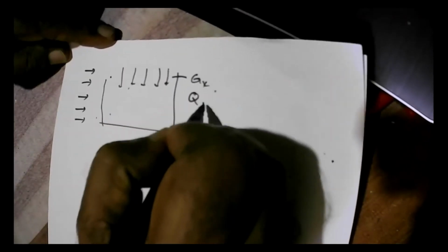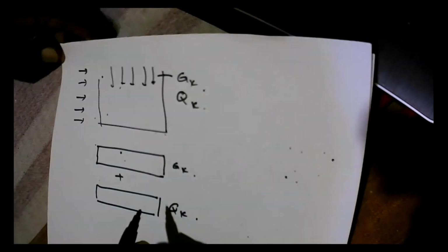It's carrying the vertical load and the lateral load. So the vertical load can be due to GK and QK. So due to GK, you get a stress diagram like this. This is uniformly loaded. So this is due to GK effect. Plus QK also you'll get an effect like this. Plus due to wind load, you can get an effect like this.